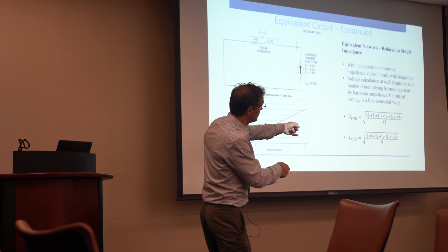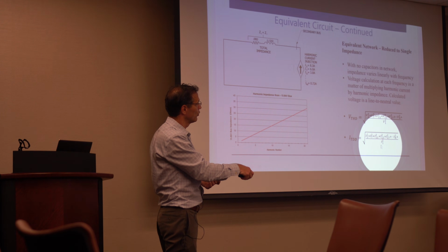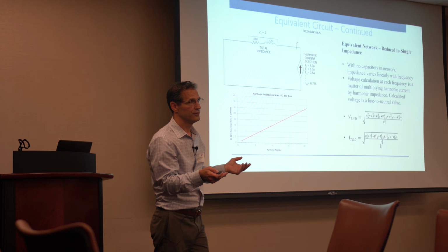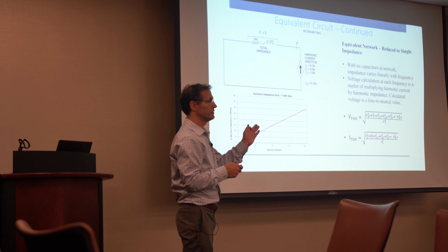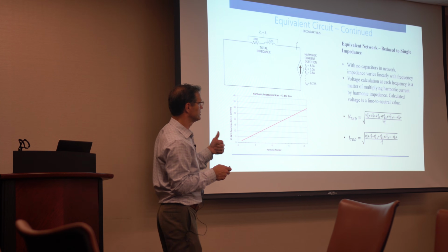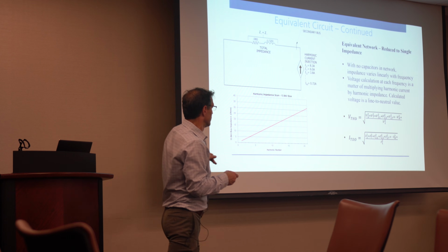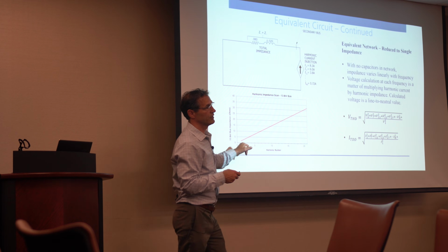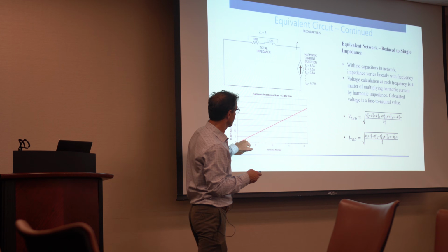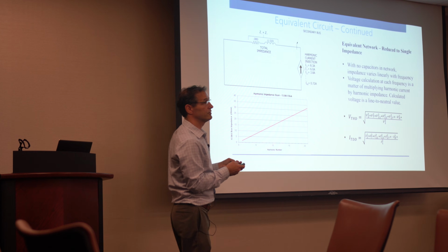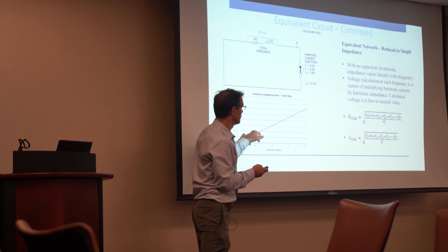So you can do the same thing with ITD, the total demand distortion. In that case, this I1 is demand current, but it could be the instantaneous current. In that case, it would be just the I1 network. And then again, sum of the squares, square root gives you VTHD, ITHD, or ITD. That's the premise here. So we use this curve. This is a good reference line to keep track of, and I'm going to continue to use this because this is dominated by the source impedance and the transformer impedance, and really the transformer impedance dominates that impedance profile.